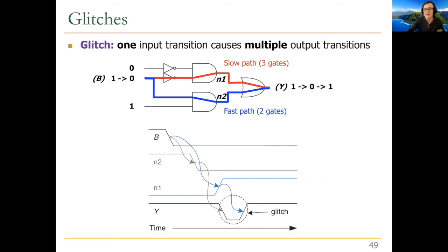That's what I mean by what I said. But to be able to do that, you need to add some other function of the inputs as part of another input to the OR gate. So that becomes a 3-input OR gate. Of course, it's not very desirable, and as a result, you may avoid the glitch, but now your area increases. So if these glitches are not a problem in your design, and make sure they're not a problem in your design, then I wouldn't worry about them. But you need to make sure that you don't create the problem of glitches by using a glitching output somewhere that's important.